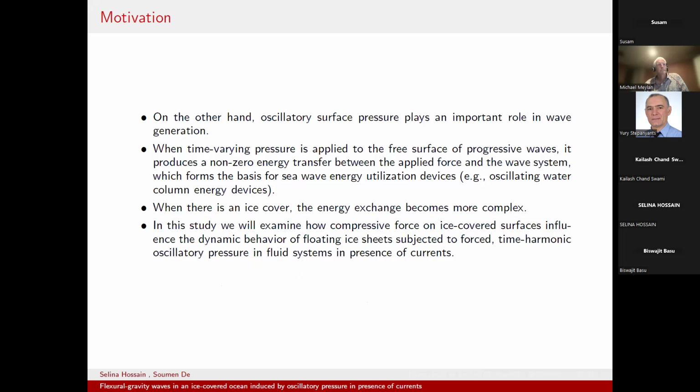On the other hand, the oscillatory surface pressure plays an important role in wave generation. When time-varying pressure is applied to the free surface of progressive waves, it produces a non-zero energy transfer between the applied force and the wave system, which forms the basis for sea wave energy utilization devices like oscillating water column energy devices. When there is an ice cover, the energy exchange becomes more complex.